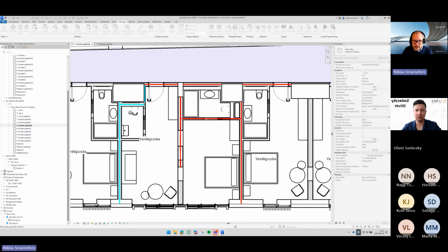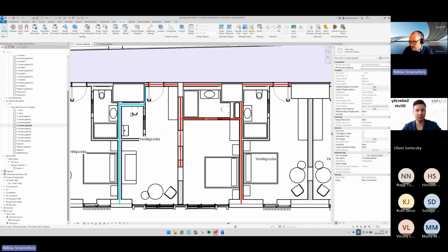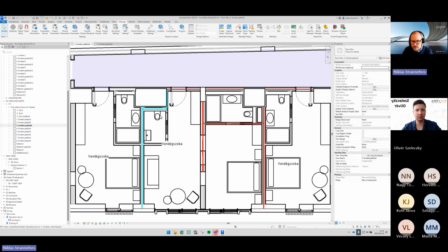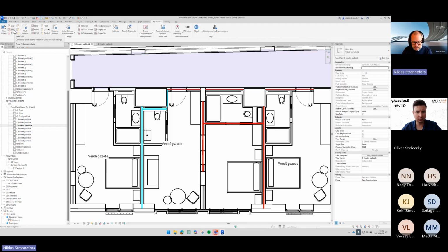Go around placing. Double click on escape, sorry, to end the command. So keyboard shortcuts, once again, if you set one, W2, place where you can, and then just press escape twice. You can double click on escape to finish that command.